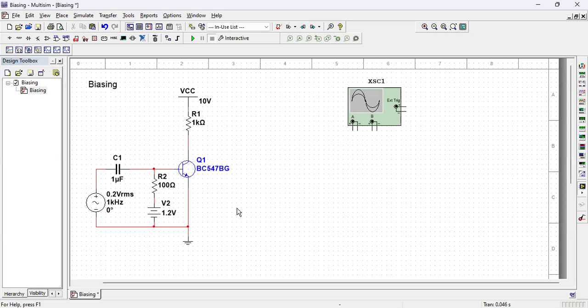One thing more I shall add. I shall add a resistor here at the emitter. Why? See, base emitter junction resistance is very small. So, if your measurements of signal and this DC voltage are not good enough, then this will be a short circuit and the transistor will burn off. So, always connect a small resistor at the emitter to ground. So, you make this arrangement.